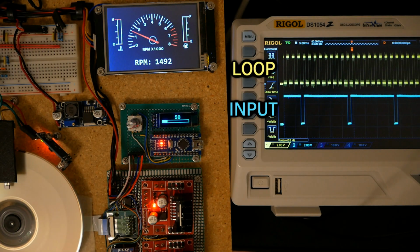An interrupt pin is a digital input that can execute part of the code only when it receives the signal from the pin. But the difference between this and a normal digital read is that the interrupt stops the processor from whatever it's doing and executes the section of the code we want, and after that the processor continues running everything from where it was left.